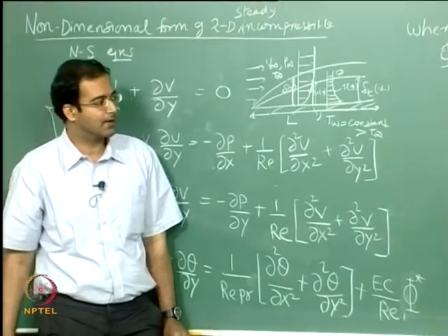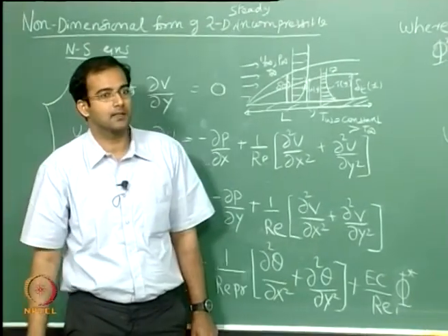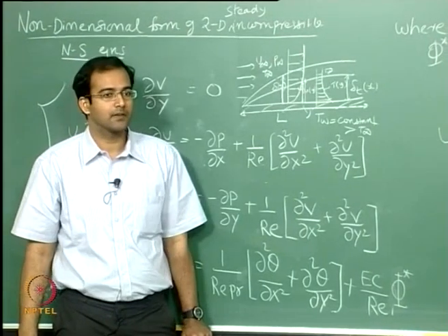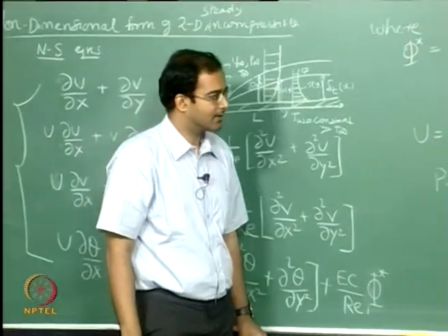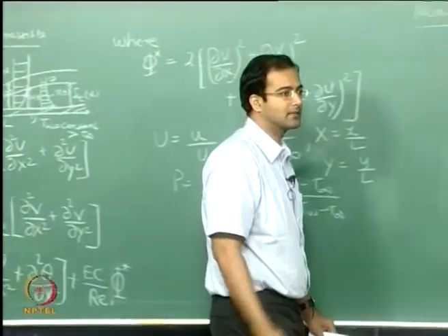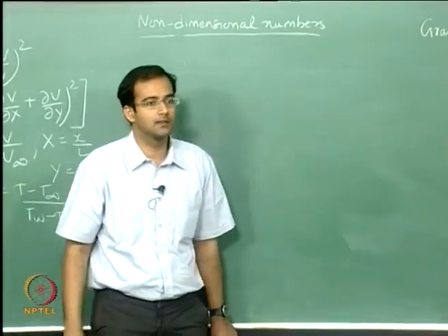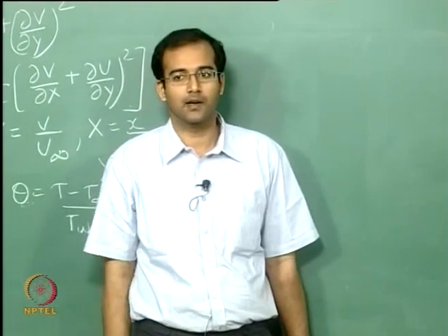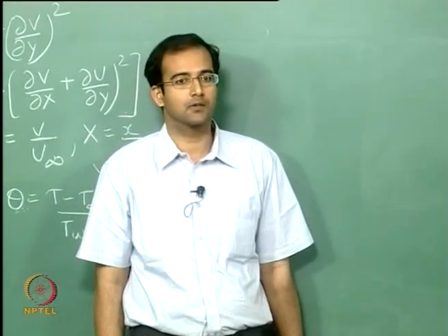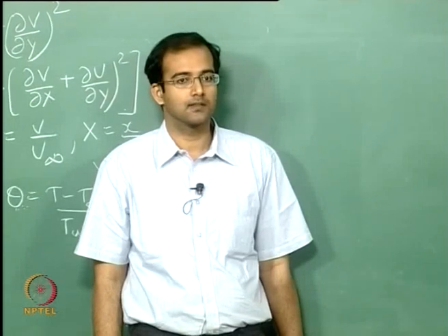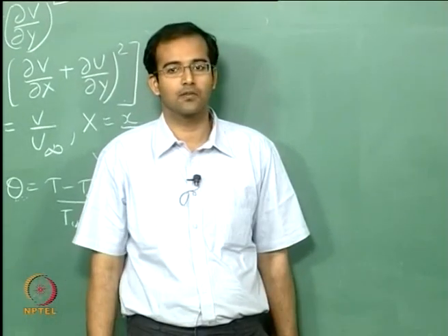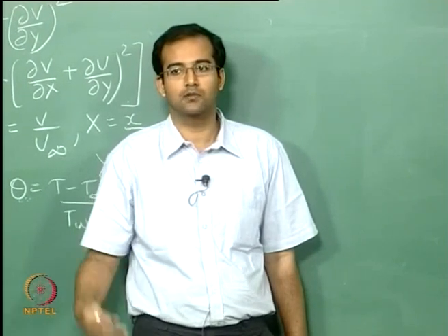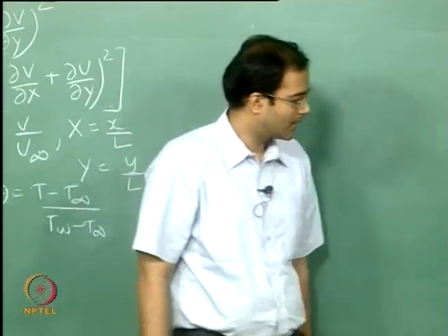If the value is equal to 1, it means all of this is happening only by conduction. If it is greater than 1, there is advection helping in the transport of heat. So when looking at convection, you are looking at Nusselt numbers greater than 1, where the higher the Nusselt number, the better the heat transfer rate augmentation due to convection.